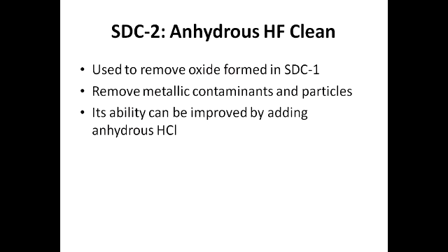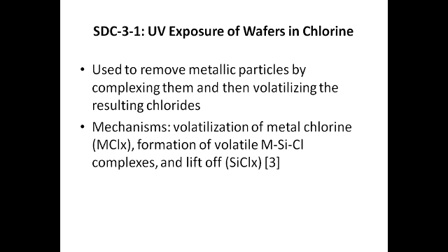The second step is to use anhydrous hydrogen fluoride to remove the oxide formed in the first step. It also removes metallic contaminants and particles. The effect will be improved by adding anhydrous hydrogen chloride. The last step is to remove particles by exposing the wafer in chlorine.